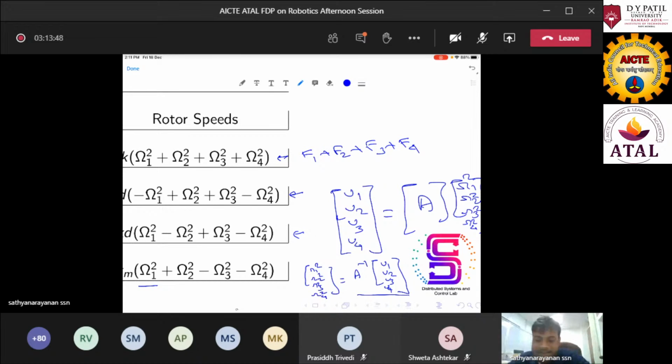So what Pixhawk does is that once you calculate this, you will normalize the values between -1 to +1. Once you normalize the value to -1 to +1, the omega for -1 is mapped to some scale, 1000, and for positive one it is mapped to 2000, and in between, 1500 is used to hover it.